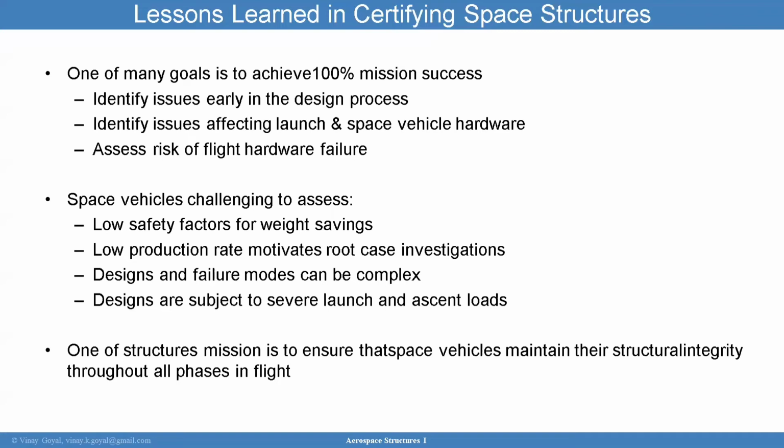But that is challenging. And, as I showed you earlier, the factors of safety can be as low as 1.25 for qualified structure, 2.0 when you're not qualifying the structure through testing. And so the low factors of safety are really driven by weight savings, but also mean you have razor thin margins. Not quite 100%, because you're designing to A-basis, so that protects against statistical variations, but it also protects us against the loads, the limit loads that we talked about. So you have that as well.